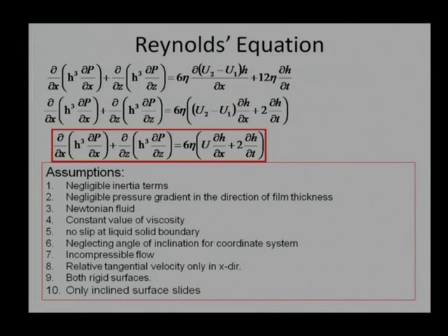Even in liquid cases, many liquids can be compressed by 1% or 2%. So, assuming incompressible flow provides maybe 90 to 98% good results, but not 100% results. If you require really 100% accurate results, then we should account for the compressibility of the liquid itself. However, for the gases, this assumption cannot be made. Gases are compressible under pressure, they reduce in volume.